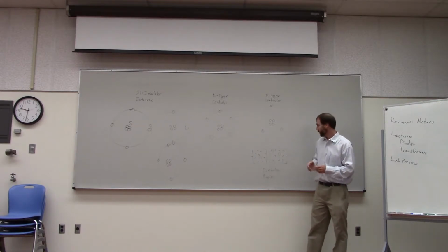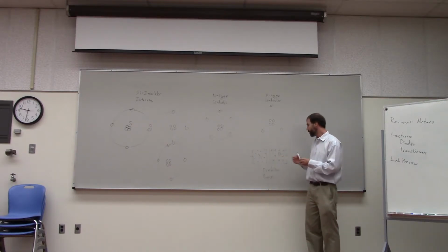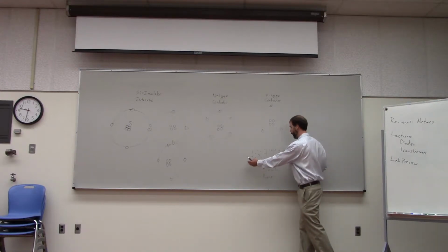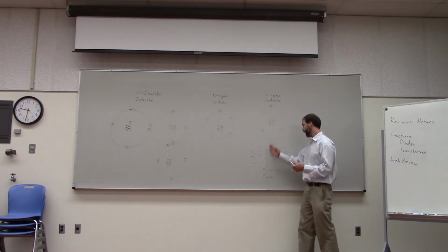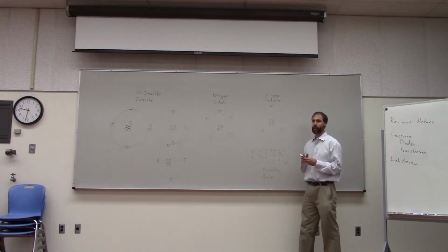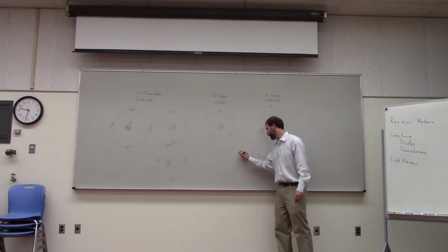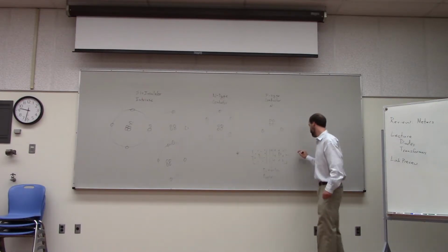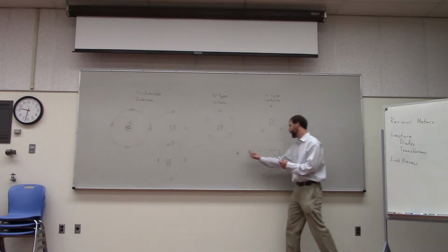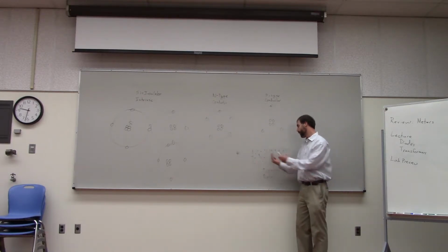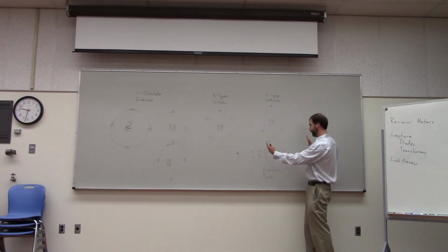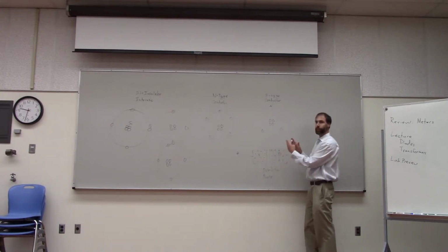So if you don't apply any voltage to your diode, then you have this depletion region and the diode does not conduct. If you start applying a small voltage, I believe a negative voltage over here and a positive voltage over here, then you're pushing more electrons in from this side. So it's shrinking this depletion region.